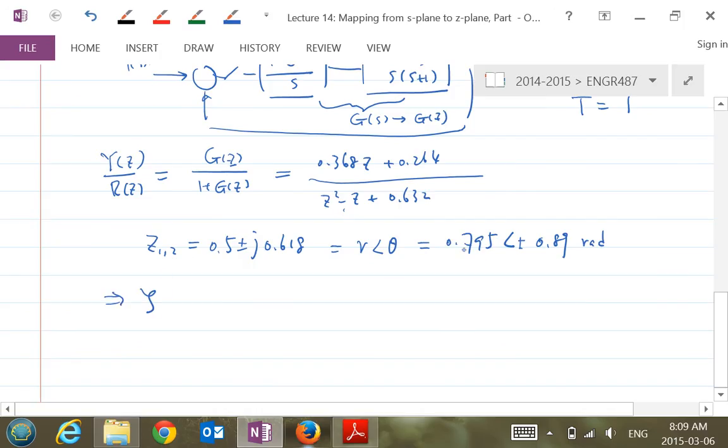based on these two poles here. Based on these two poles, meaning assuming you don't know anything about the sampling time. Just assume you are given this one here. Then you plug it back into the equation. You will get zeta equal to 0.25, and omega n equal to 0.9191. So that's your zeta and omega n corresponding to this discrete pole.